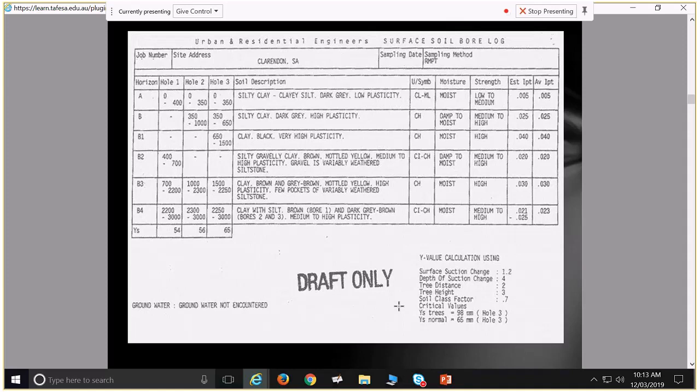Any other information we can get from that table? Is that like, for instance, 54 either way, or is that like from the lowest to the highest? Yeah, lowest to the highest. Yeah, 54 mil. What should be bad? If that's not bad, what should be bad? Around 100 mil or so. Or plus. Yeah, so 100 mil, that's when you're getting into extremely reactive soils.